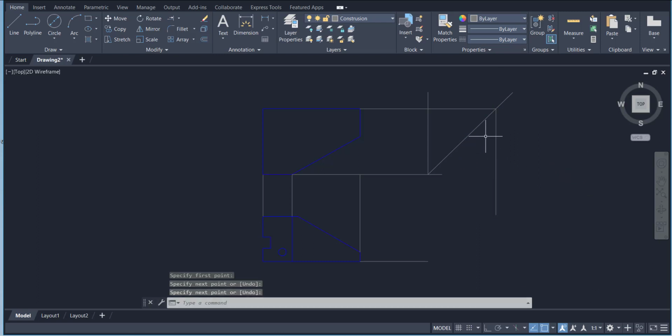Straight line. So basically this straight line is transferring the view, and this line from this side, every line which touches this middle line, we have to make it like from here. So this line, I have to extend and just trim these extended lines like that. So here this is our miter line. So every line from this view will meet here, and from here we need to transfer it at 90 degrees to the side as the right side view.